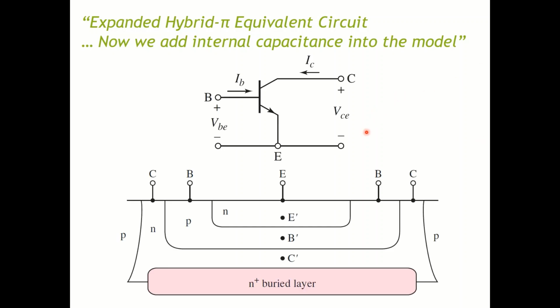So as you can see, this is your normal BJT, right? In manufacturing, you actually have different layers of N-doped and P-doped semiconductor, typically silicon. So if you look in here, for example, the substrate is a P-type substrate with an N plus buried layer, okay?